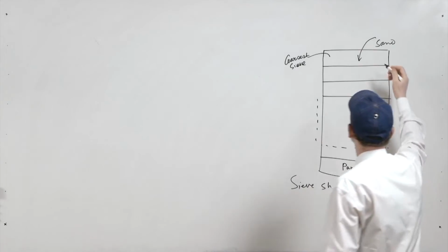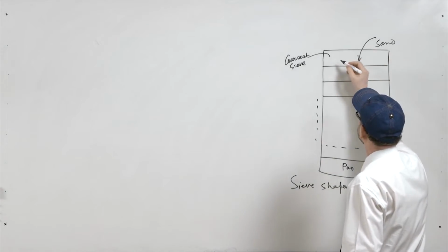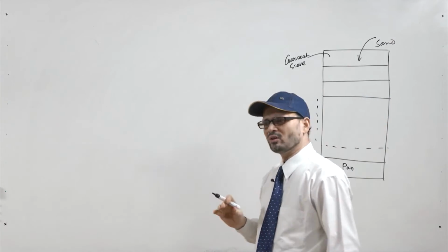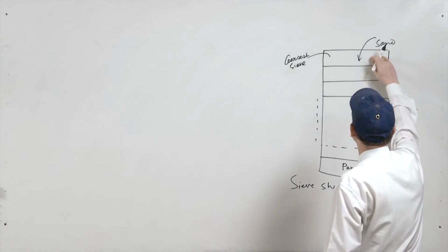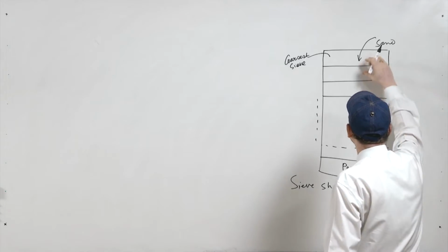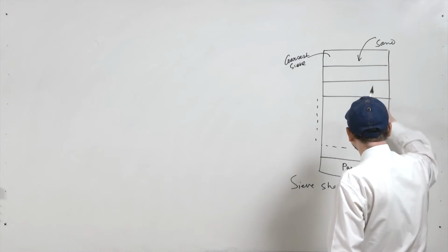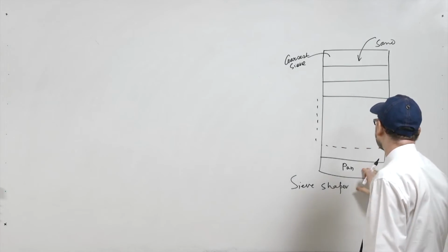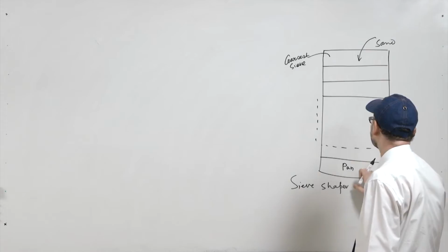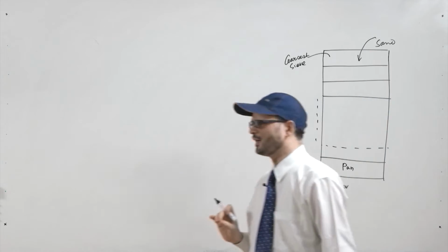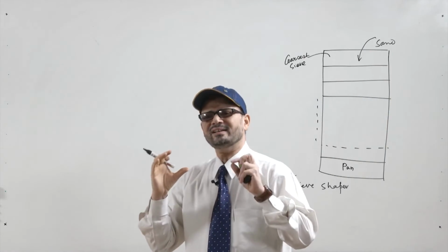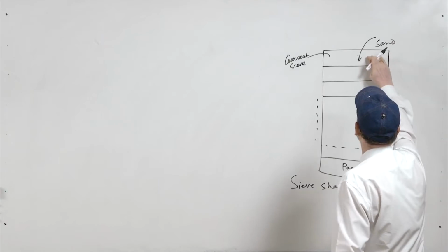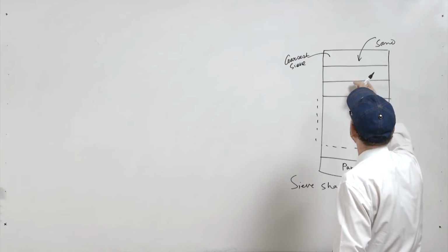During the vibration, the coarser particles remain at the top sieves, whereas the finer particles get sieved and gradually come towards the bottom, and in the end very fine particles will come into that pan. So, this way if you take a certain quantity of sand, then certain quantities will be retained on these particular sieves.